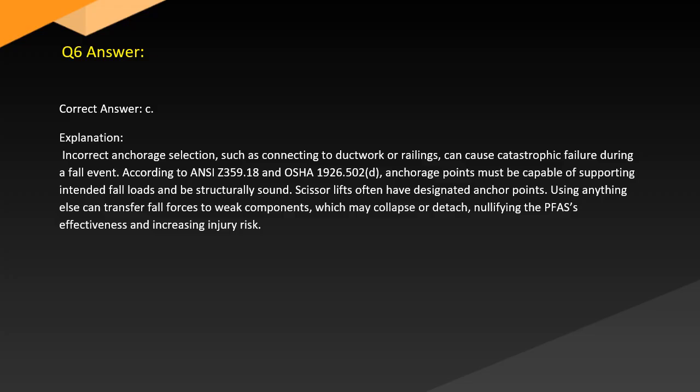Scissor lifts often have designated anchor points. Using anything else can transfer fall forces to components which may collapse or detach, nullifying the FPS's effectiveness and increasing injury risk.